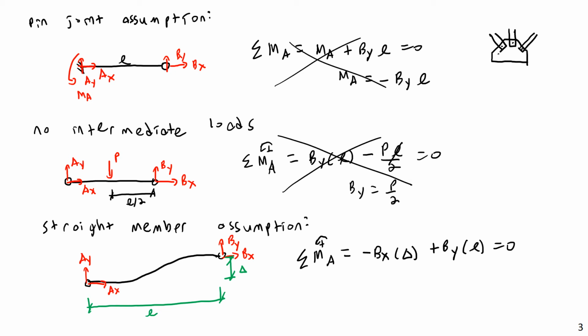We treat these as pin connections and say they have 0 moment capacity because compared to the moment capacity of the members that are connecting them, they are relatively low. But they're not actually 0. And even if I use literal pins, like literal ball bearings or actual machined pins, there would still be some friction present in that pin, so even the most ideal pin will still be able to transmit some non-zero amount of moment. So this is not perfectly possible, but again, this is an idealization.